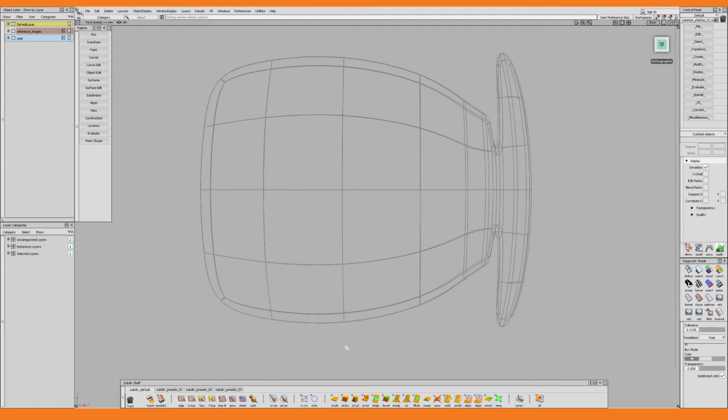Whenever you're making 3D models, you have to keep the purpose of the model in mind. So if this was an actual production model and the seat was going to be manufactured, then I would rely on curves and the profile tool to make sure that the legs were up to par. But since this is merely a visualization model, which will be used for an occasional render or two, I will kind of do this the quick and dirty way and rely solely on subdivision models.